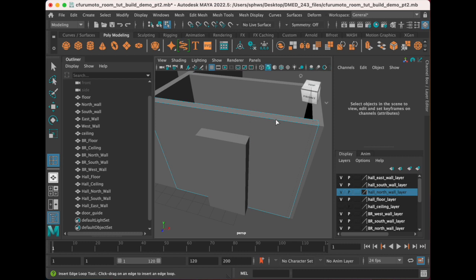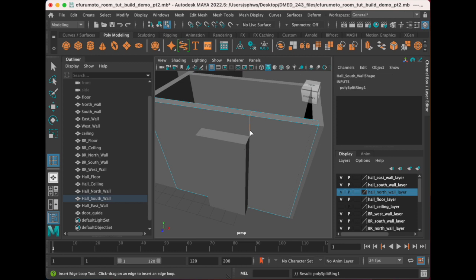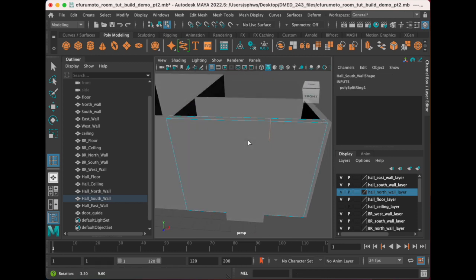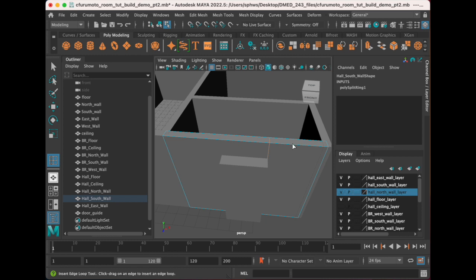So I'm going to click on one of the horizontal lines and click and drag, and you notice it creates a dotted vertical line. I'm going to have that drop off right on the edge of this door guide. So there's one side. I'm also going to do the other side. You'll notice I'm going to leave this area alone and I'm going to actually start from the other side. The reason why is anytime we're doing any insert edges, and I'm going to hit this one right here.